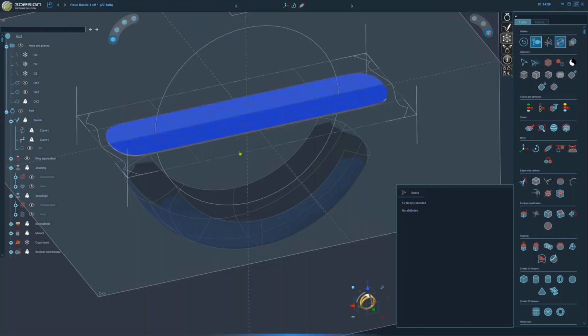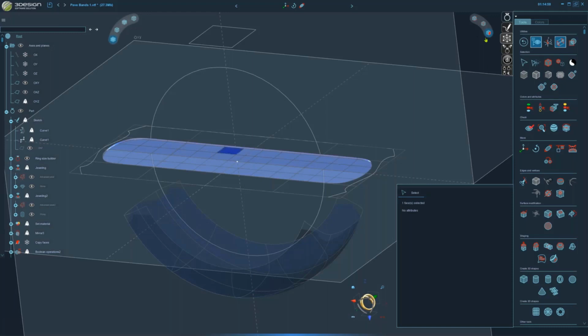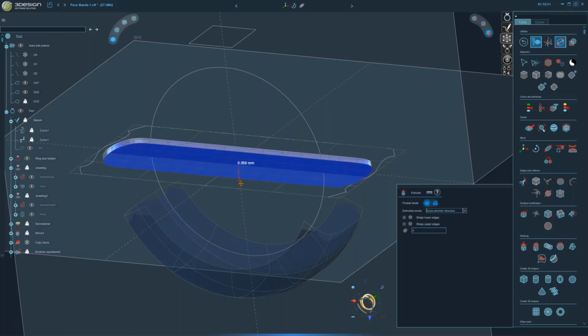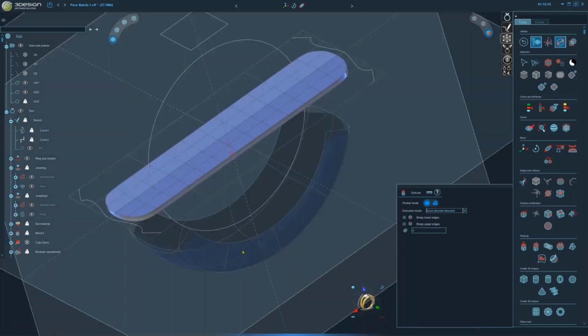Okay, so it sticks out a little bit. I need to do the backside just like we did on the other one. So I'll do my face selection again, just clicking the single arrows, and we'll do our extrusion this way. This is sinking into our ring on the bottom side. We need that good connection for the Boolean operation.